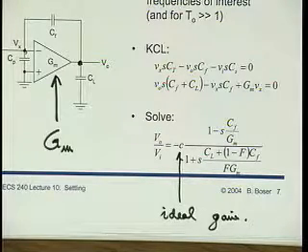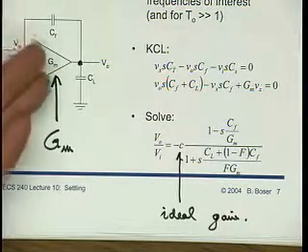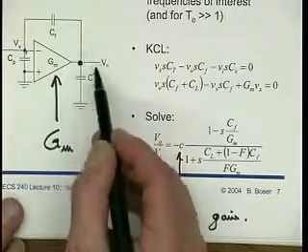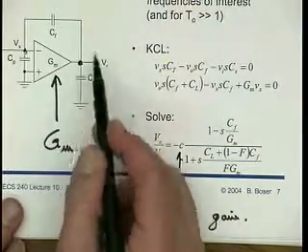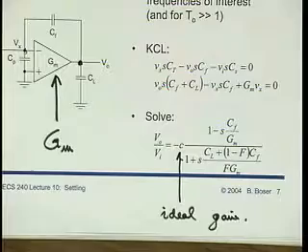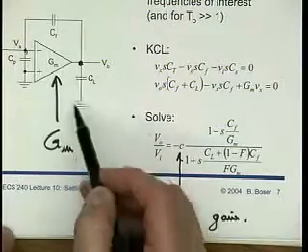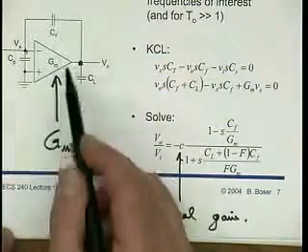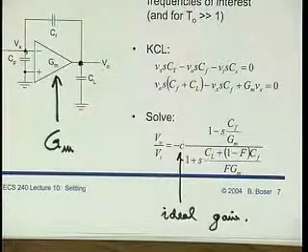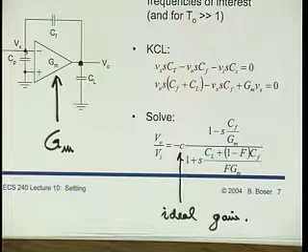And that is dead on, this ideal gain. Why? Well, because here I implicitly assumed that we have infinite gain, because I left all the RLs and ROs and whatnot out of the picture. Again, the same argument as we had used earlier, that when things go fast, the bulk of my current goes through the capacitors anyways, and the little trickle current that also flows through these current source output resistors is sort of negligible.